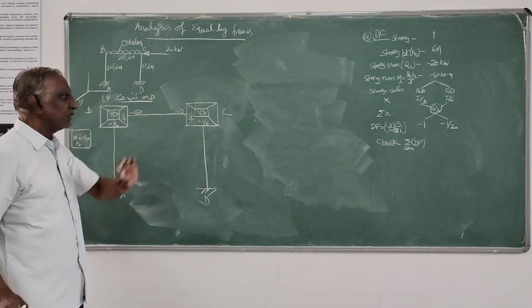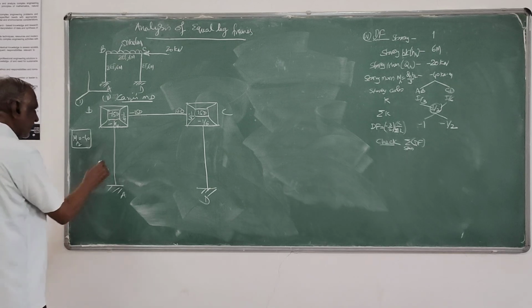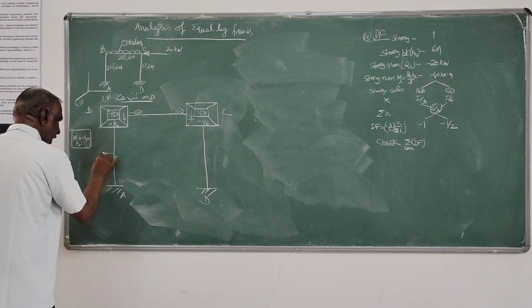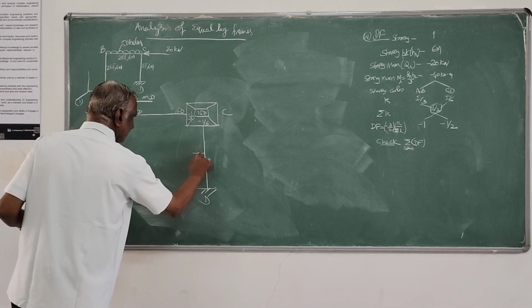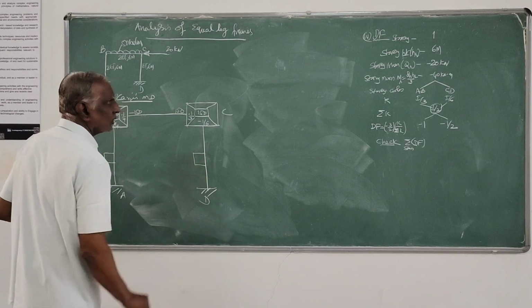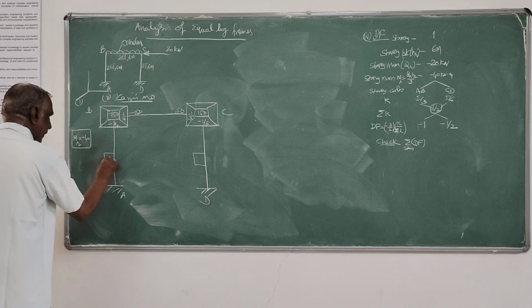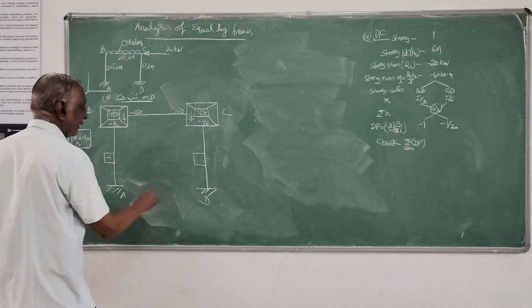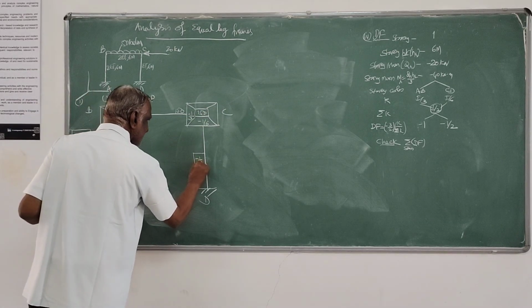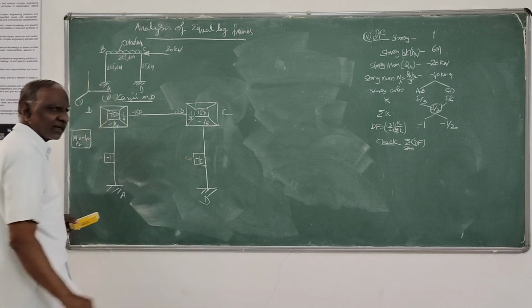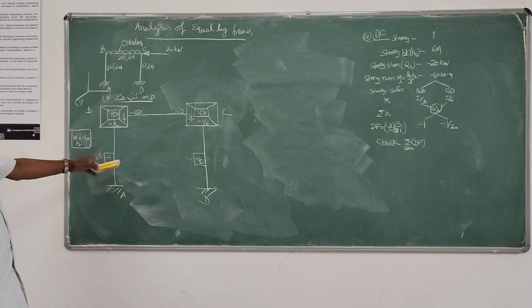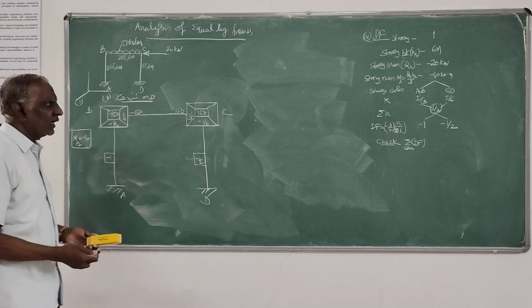So that's done. Then the story displacement factor, that is for the columns AB and CD. I will write it at the center of the columns. So for AB, it is minus 1. For CD, it is minus half. If that C is equal to 1, the column factor, because it is equivalent, that also you have to write if it is unequivalent.